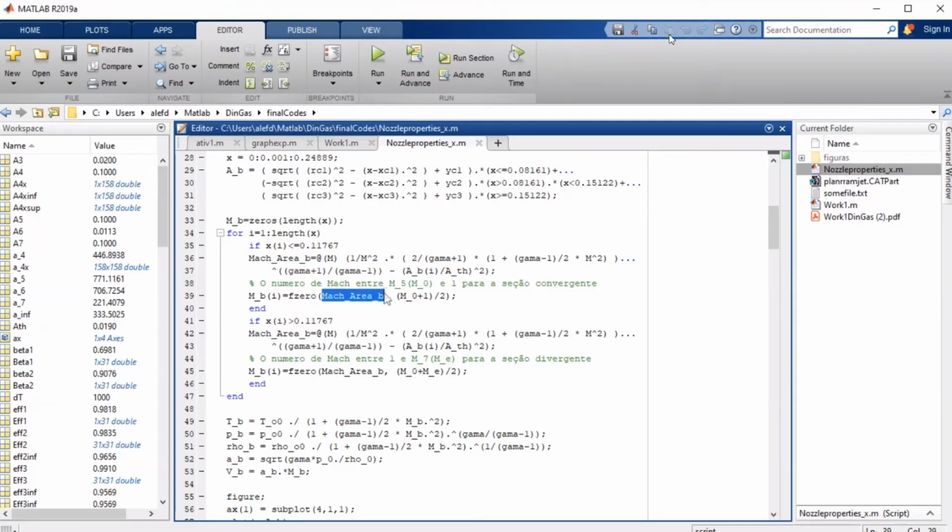I define the Mach number equation this way, and I use fsolve with this equation around the midpoint I expect. I expect the value of the flow to be somewhere between the Mach number at the inlet and 1, because it should be 1 at the throat. So I just took the average value for around where I should take it before the throat, and I took it at the throat too.